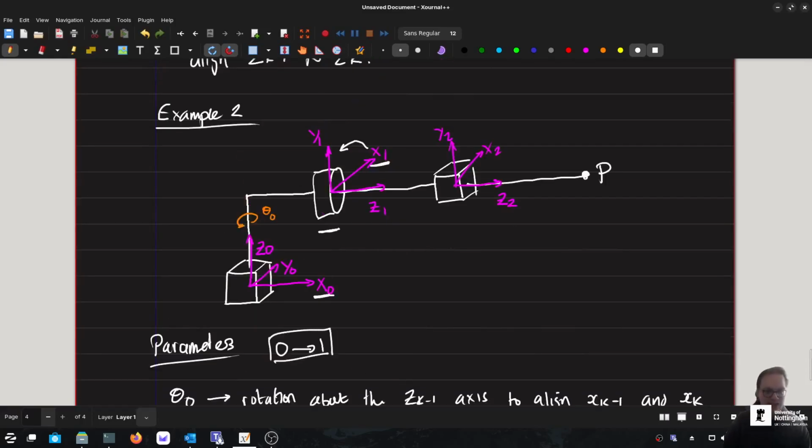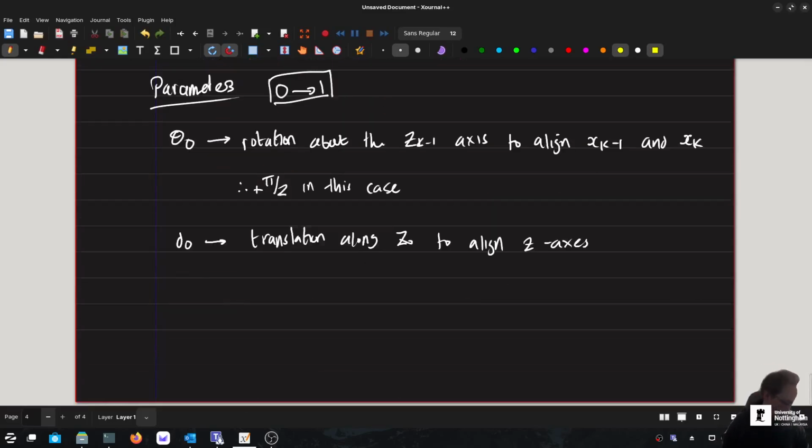So in this case, you can see that we are going up from here, up, up, up, up. And we're going to stop there because although we haven't fully aligned it, of course we've got to translate along the x0 still in order to do it, moving up this amount along the z-axis would align the axes until we then move along the x-axis. So that is our d0 in this case. So we haven't got a variable for it, but that's what d0 would be.